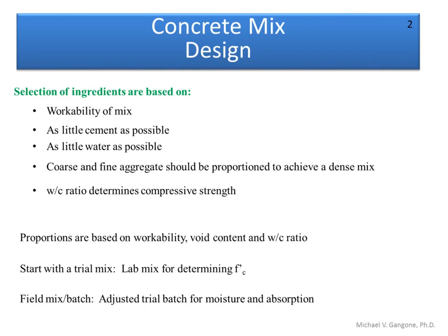So the cement and water together form the cement paste that acts kind of as the glue, as we mentioned previously, all right? Well, when we think about shrinkage in the concrete, shrinkage is due to water leaving the concrete. So when the water leaves or evaporates from the concrete, then the concrete will start to shrink, and that shrinkage can create stresses in the concrete and create cracking. All right, so the more water that we have, the more shrinkage will occur, the more cracking that will occur, and we can create some problems in that particular case. All right, so that's one thing about when we think about water.